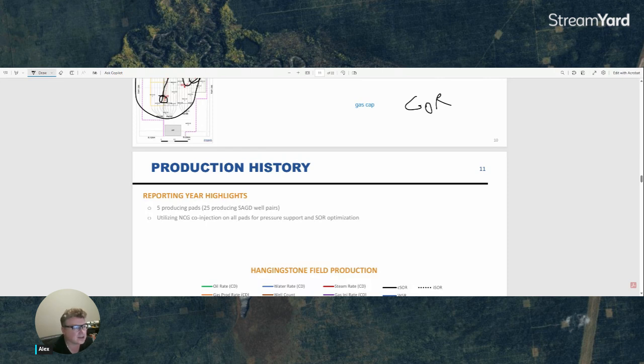And K is the rate of flow per unit cross-sectional area under the influence of a unit gradient that has dimensions of length cubed over length squared times time, or length over time, but should not be confused with velocity, for example. So I know I'm getting a little bit more technical here, looking at some of those legacy definitions of hydraulic conductivity.